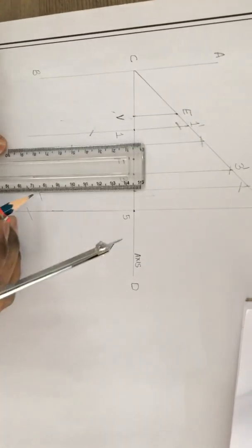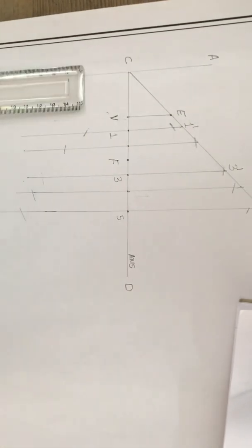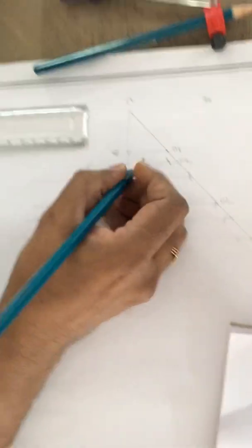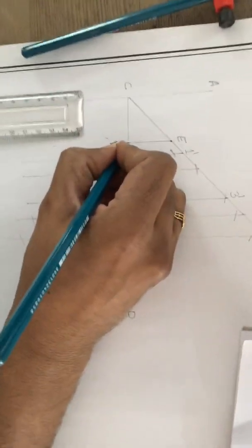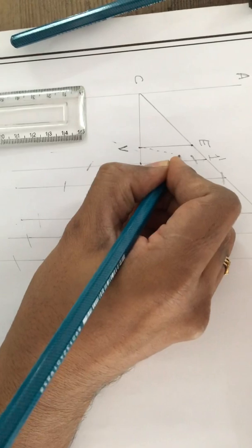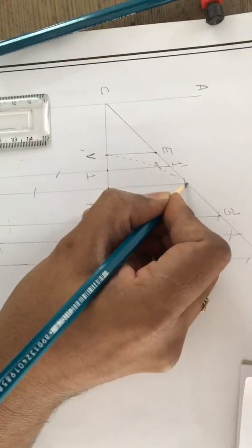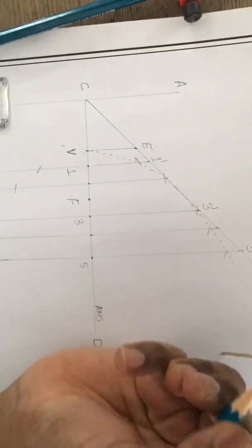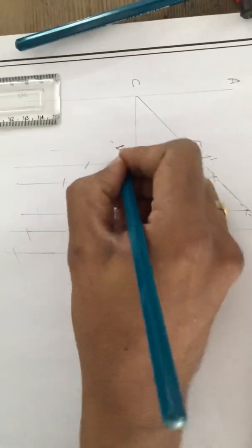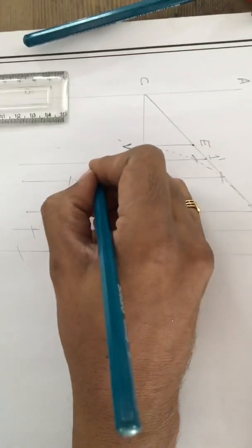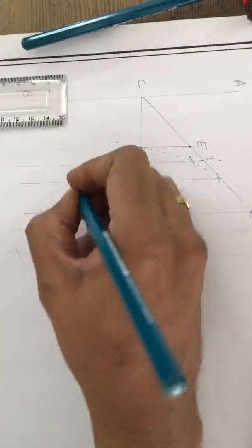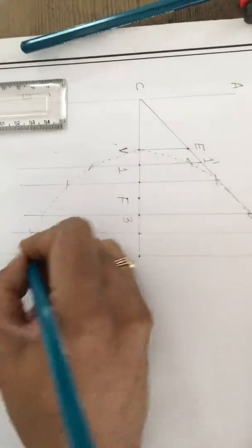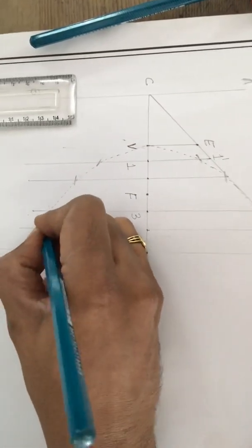Draw a parabola curve. I hope you are getting each and every point that I am speaking about here. Later, take the H pencil and from the vertex you are supposed to locate the points passing through all these cut marks where I got the intersections. Getting it, students? These are all the points of intersection. Later, even down below the C, you are supposed to mark all these curve points with a pencil, and do not draw a direct line with the HB pencil. That won't give you a smooth curve.